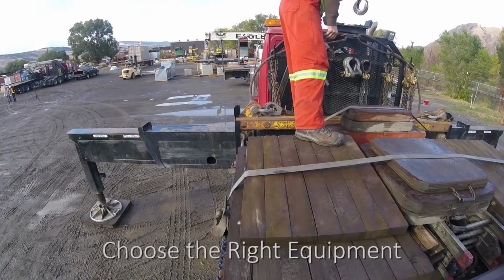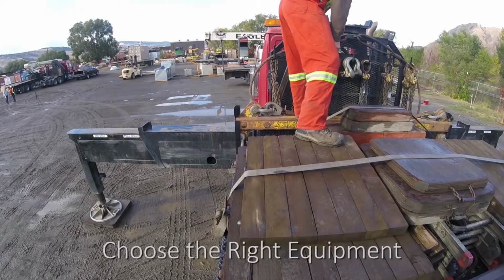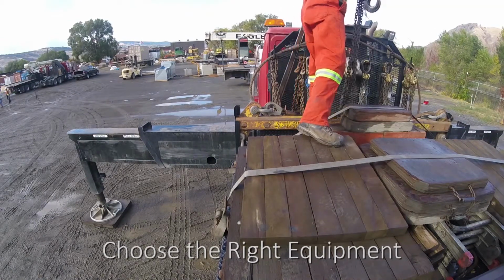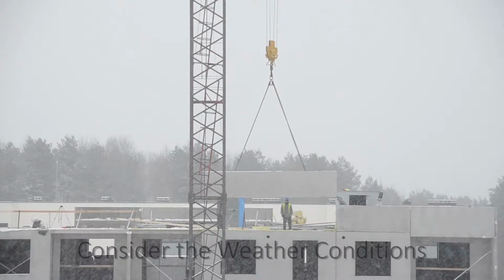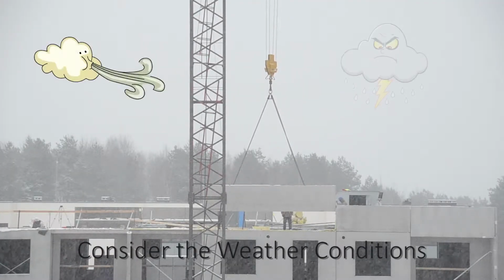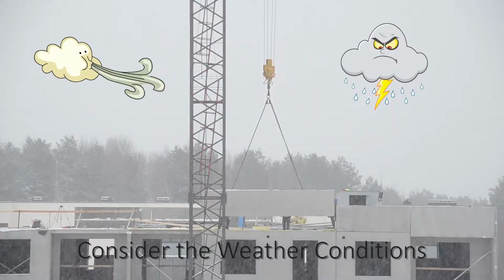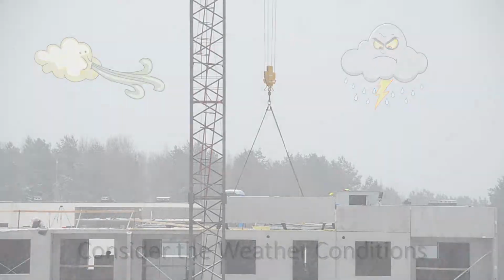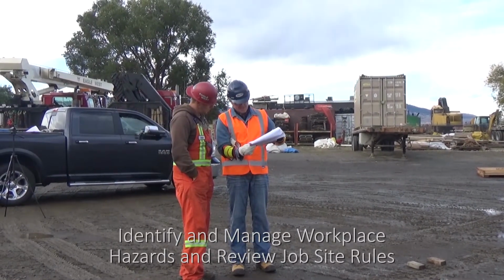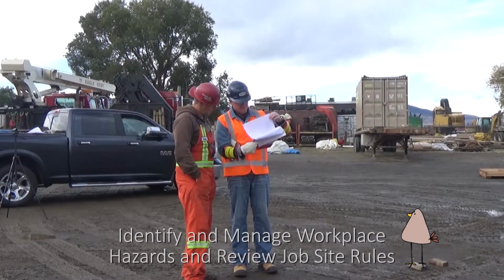When planning for hoisting operations, you need to consider the load and its weight, and the types of equipment that will need to be used, and choose the right equipment for the job at hand. You'll need to consider the weather conditions, such as hot or cold temperatures, or wind and lightning, and how this weather may affect the workers, the equipment being used, and the load being lifted. You will need to identify and manage any workplace hazards, review the job site rules, and determine what permits may be required.